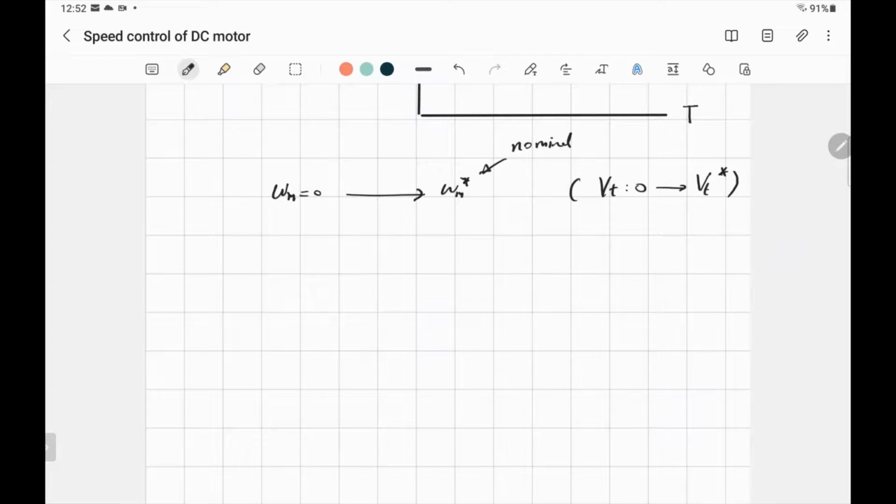Does it make sense to you? You make the field weak, you get high speed. Why? One point bonus, so answer this question. Does the field current kind of work like a brake against the motor? Actually, the opposite. When the field current decreases, the speed increases. Right. But the field current is what creates the flux which controls the motor. It reduces the flux, that's right. So if the field current is lower, will the flux be lower? The flux will be low. That's right.